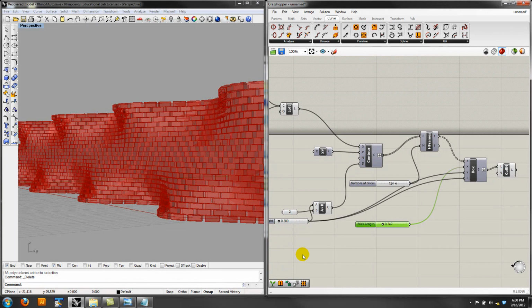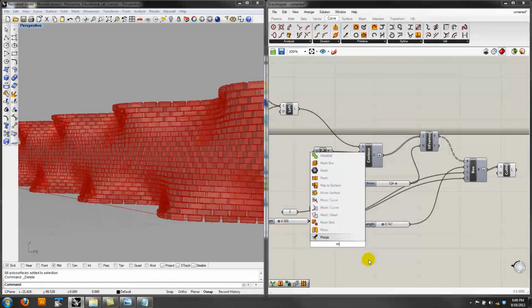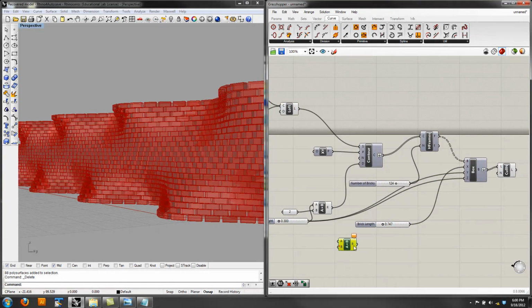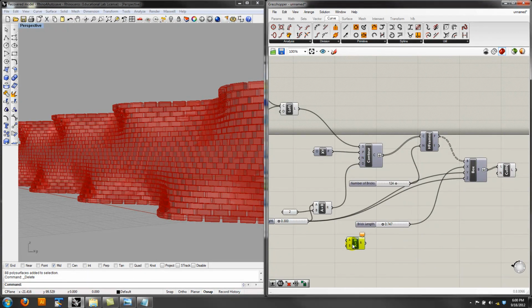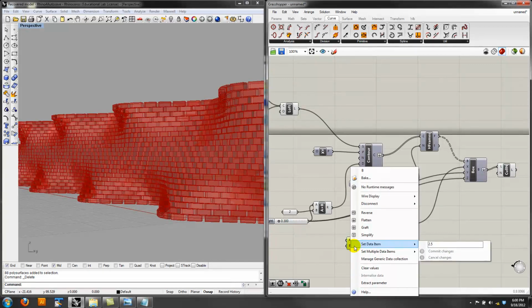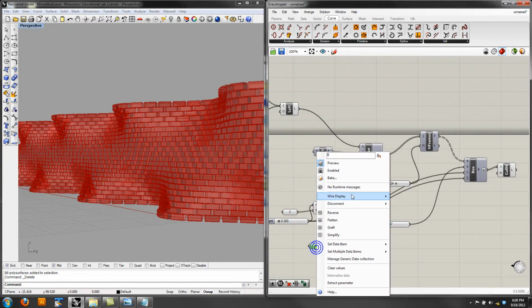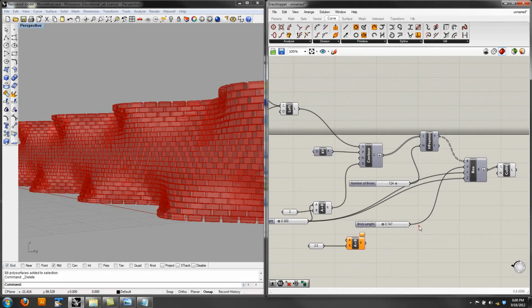You can kind of program those in. So I could say something like the length of the brick should be 2.5 times the height. I could do multiplication, and I could break this out and say 2.5. Actually, I just said it explicitly. Let's extract a parameter, and let's just call this 2.5, so I can see what that's supposed to be. Okay, good. And let's plug in the z, and the output is like 0.75. Yep, close enough.